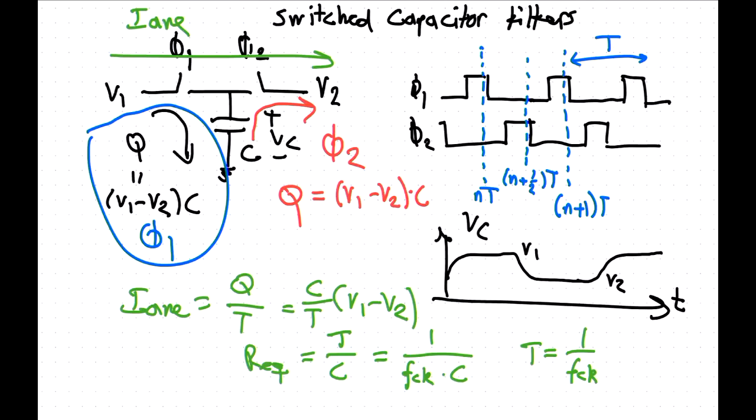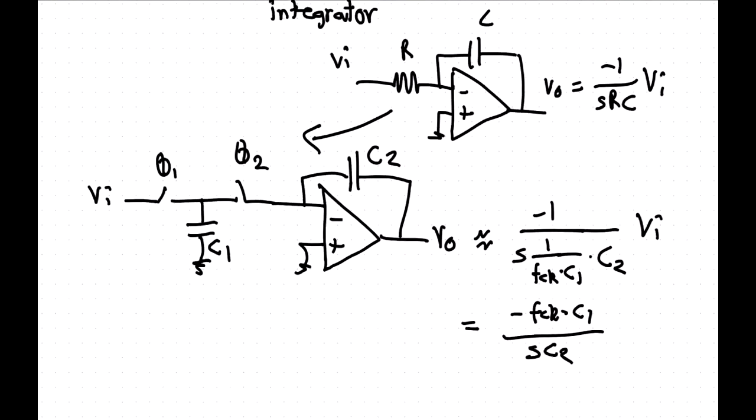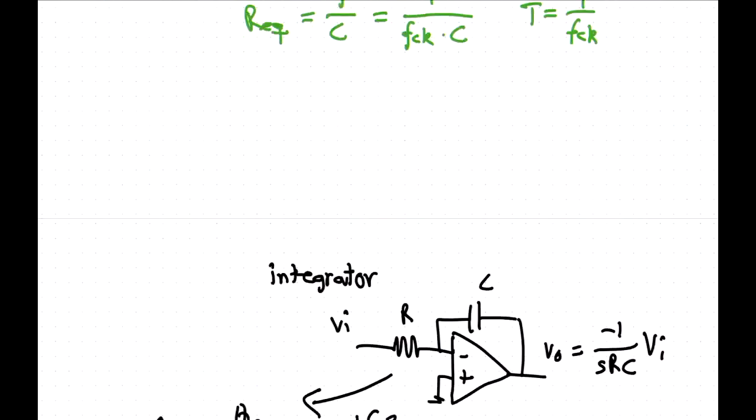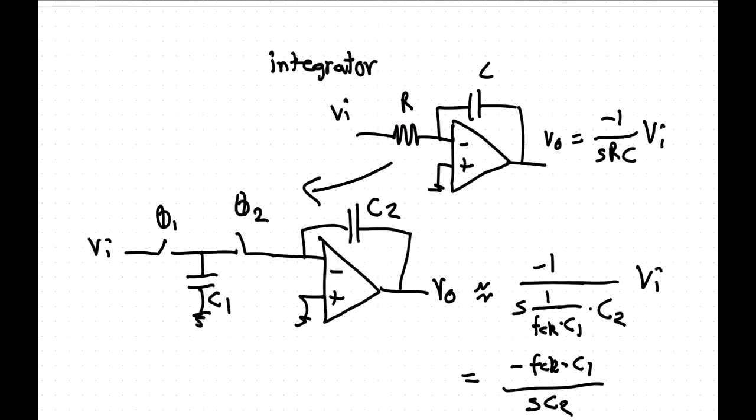So the reason that this is good is that, hang on, what am I here? Okay. So if you look at the filter pole you get from this, we got a pole which is RC. Now, normally when we make filters, we know that the sampling frequency is given, so we need to make our anti-aliasing filters at whatever frequency.